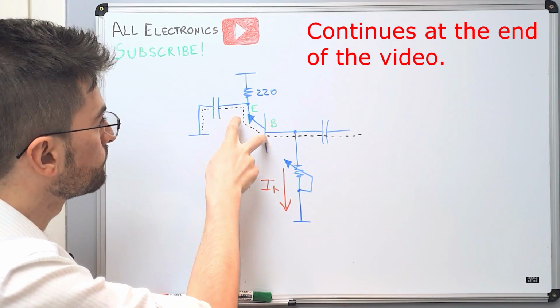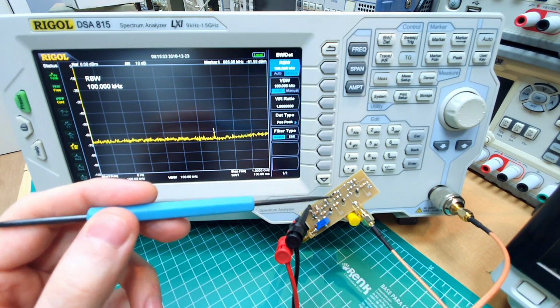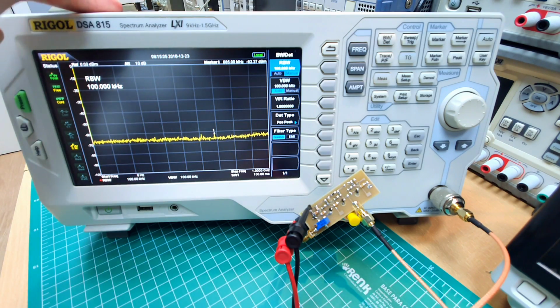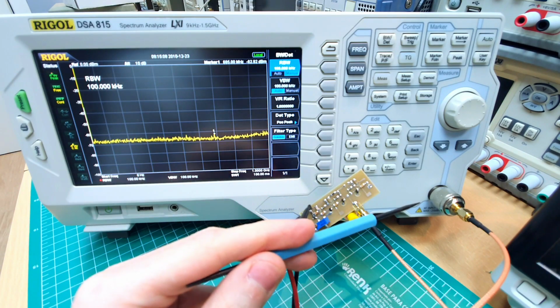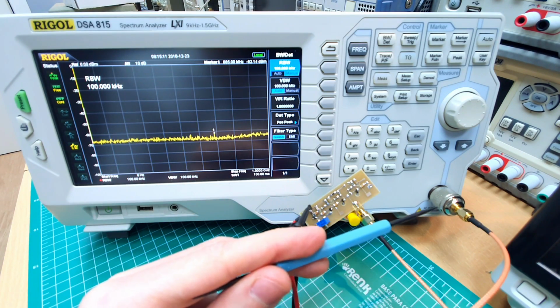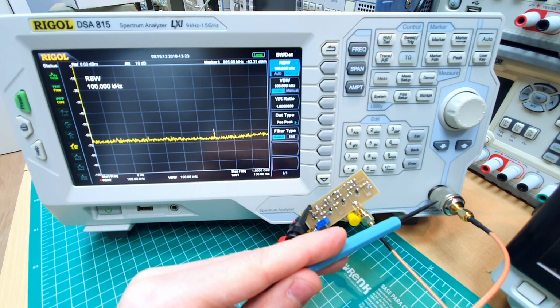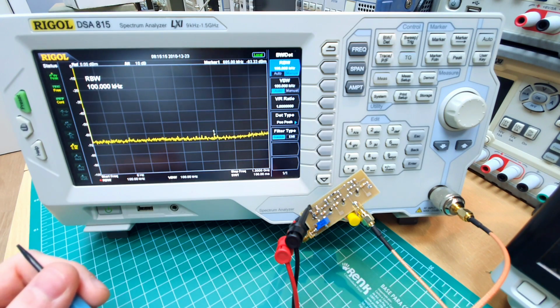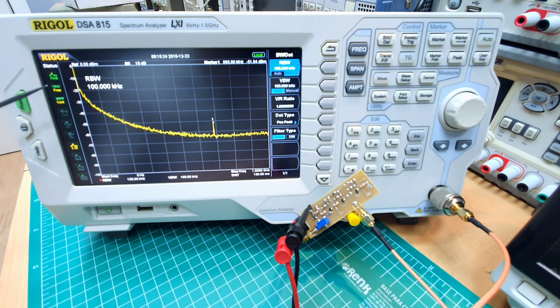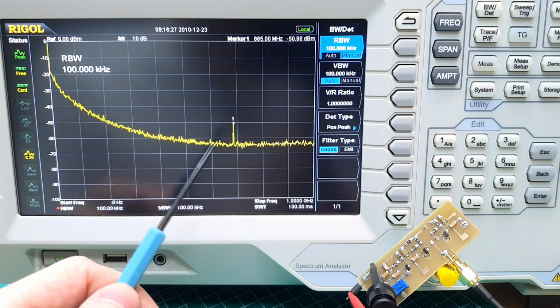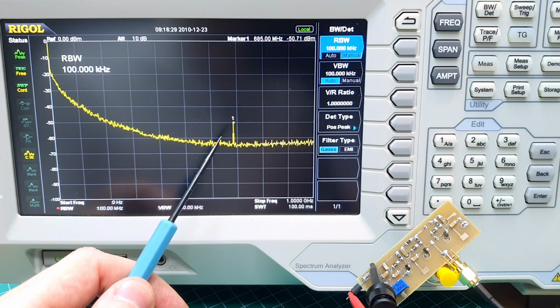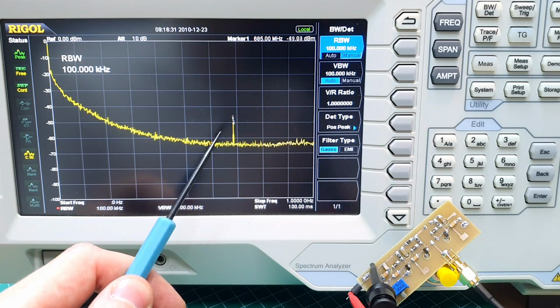junction. Now we have the noise generator connected to the spectrum analyzer, properly terminated to 50 ohms. In the example using the oscilloscope, it was not. Now it's properly terminated. And we're going to turn on the power supply here. We see this roll-off here. A lot of power at lower frequencies, less power at higher frequencies. And for the video, we are leaving this spurious here, that is the signal from my wireless microphone.